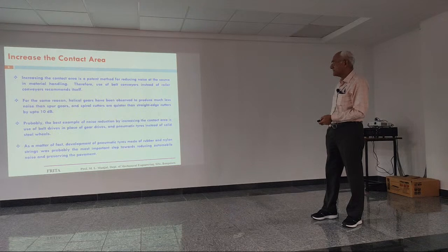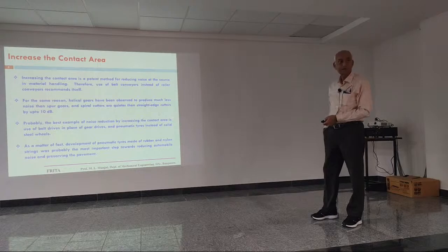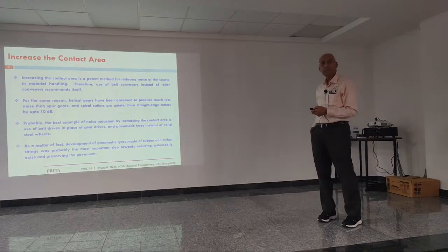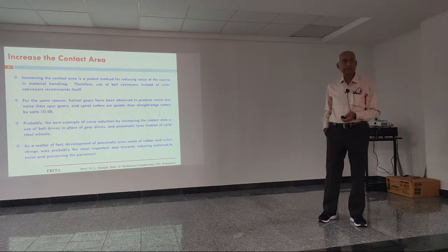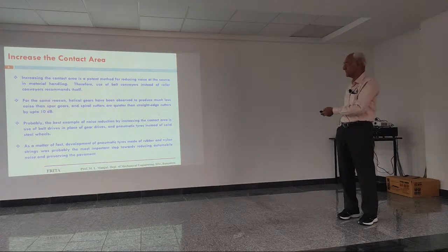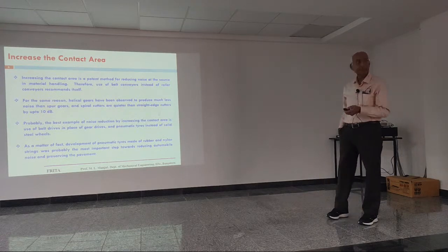Now probably the best example of noise reduction by increasing the contact area is the use of belt drives in place of gear drives. All of you know that belt drives are quieter than gear drives, mainly because the contact area in a belt drive is more.